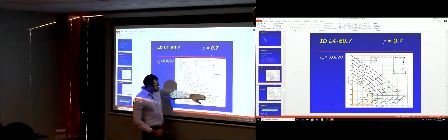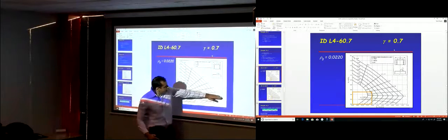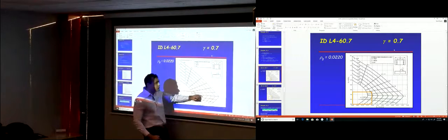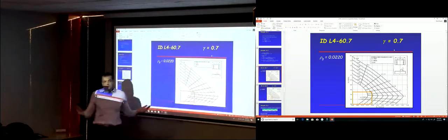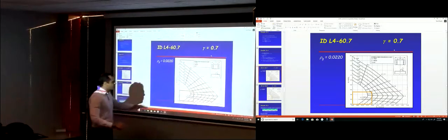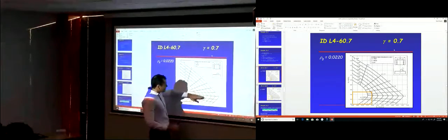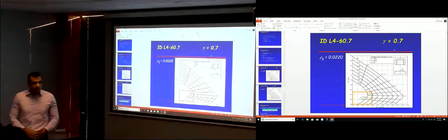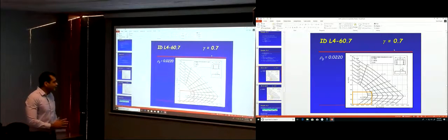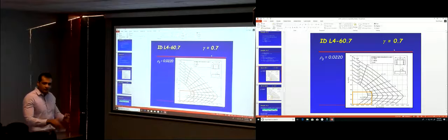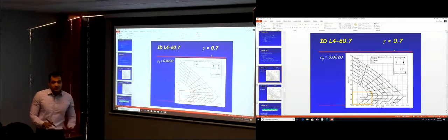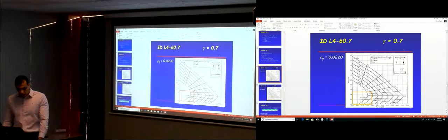If your point was below that one line, this one, Fs divided by F yield equal to 1, if the point was below that line, then phi is not 0.65 as you assumed. As long as the point that you get on the curve is above that line, you're good. Your assumption is correct. So that's one last check here. And then you have to design for the stirrups, check the spacing between the bars, and so on, as you did exactly in chapter 9.